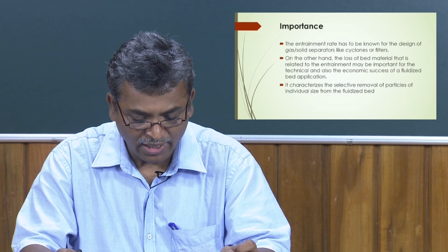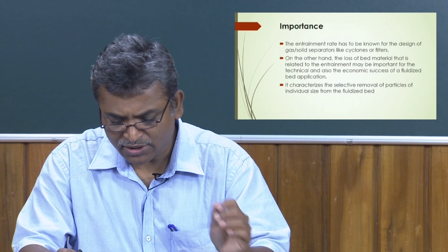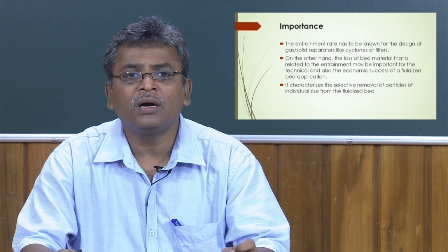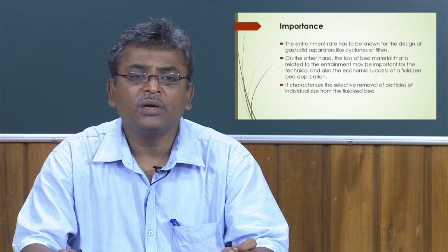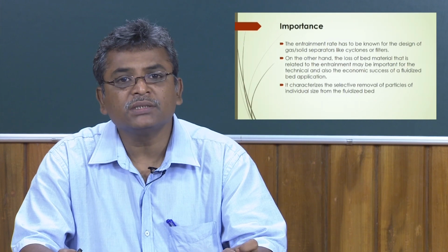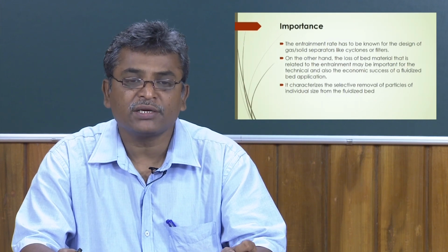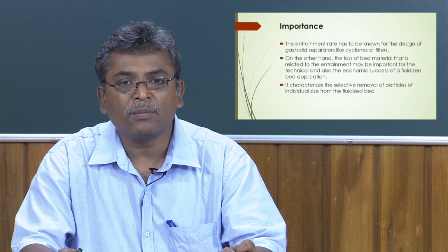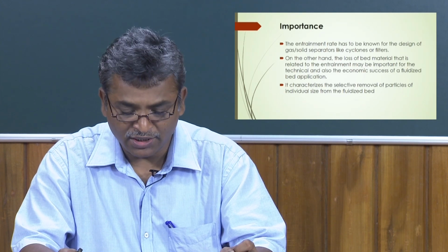the entrainment mechanism there. On the other hand, a smaller amount of solid particles will be coming down relative to the finer particles if there is high interaction inside the bed, and there will be formation of fine particles because of the interaction.